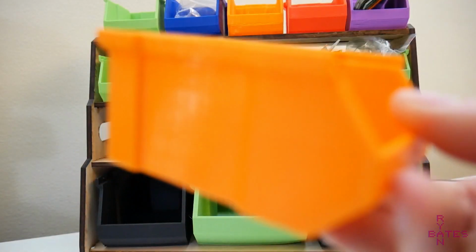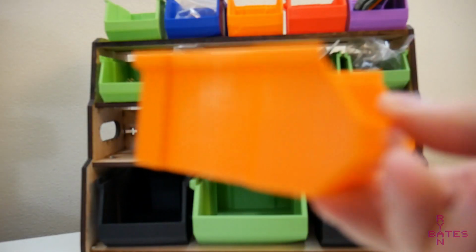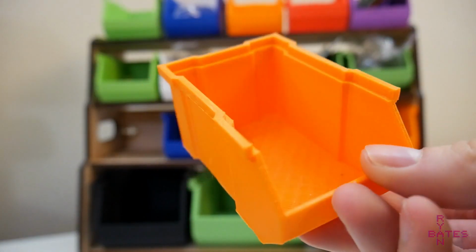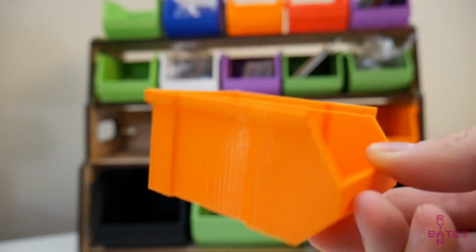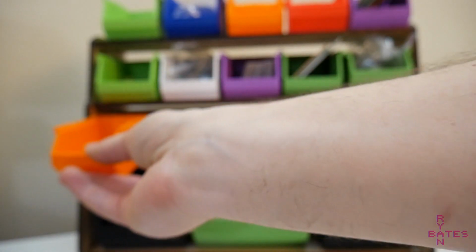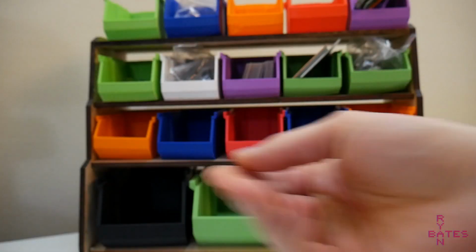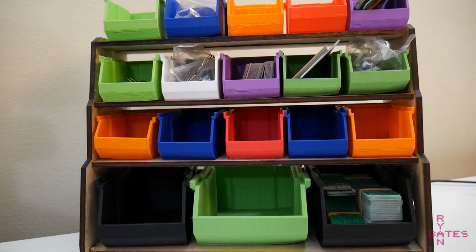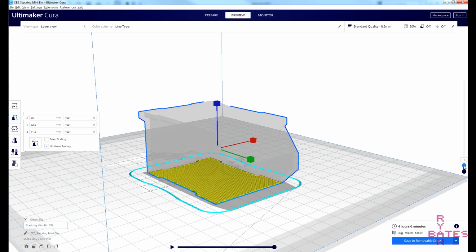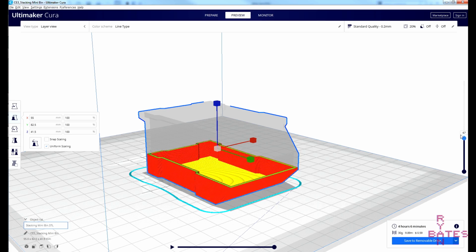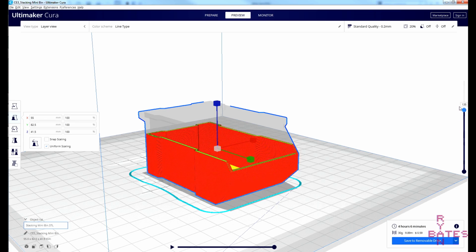Remember, design your model for the manufacturing process. 3D printing in this example is an extremely versatile manufacturing process, but it has its limitations too. With so many variables to adjust, it's possible to branch off into a path that always produces good results, and then on a different machine or one more tweak produces failed parts. Sometimes a combination of refining your CAD design and experimenting with the slicer will yield optimal results.